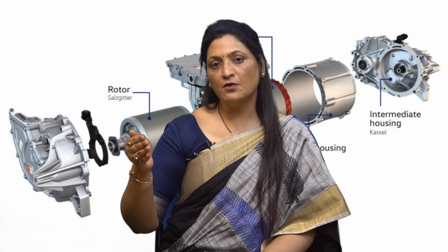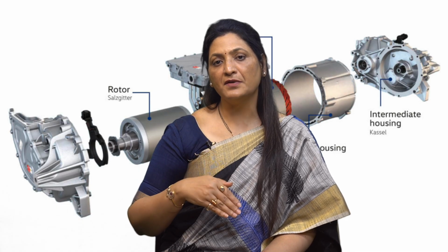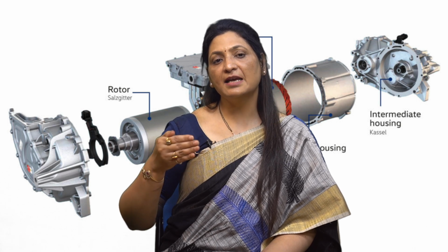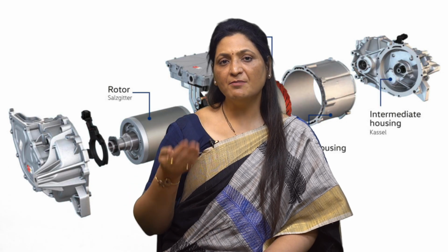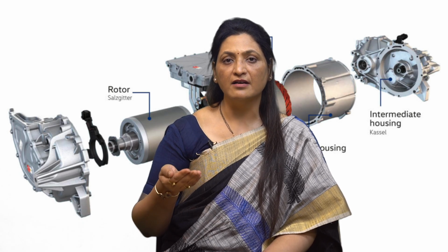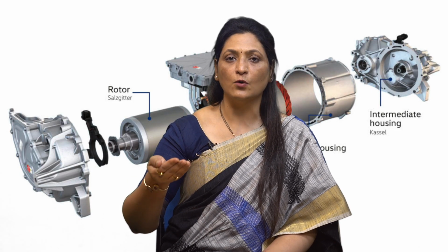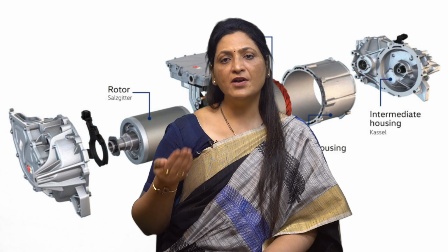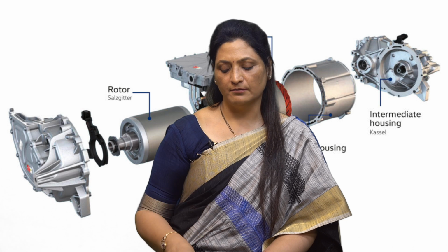The stepless variation of resistance can be obtained by using a semiconductor switch in parallel with the fixed resistance, and the variation of duty ratio of the switch gives a stepless variation in effective value of resistance. In high power applications, liquid rheostats known as slip regulators are employed to get the stepless variation of resistance. Inductors, usually in two steps, that is full and zero, are employed for limiting the starting current of the AC motors. Old drives may also employ saturable reactors for the control of induction motors.